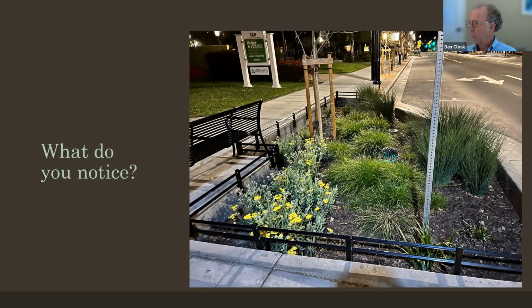So answer being that, first of all, if you recall, one of the objectives in trying to do good LID design is to avoid draining landscaped areas to bioretention facilities. So if possible, the landscaped area should be self-retaining or self-treating, meaning that if it's sloped, it runs off the site without being directed to a bioretention facility.